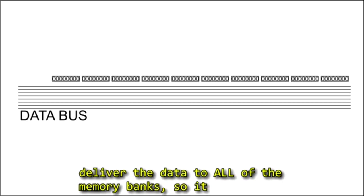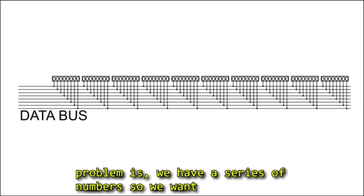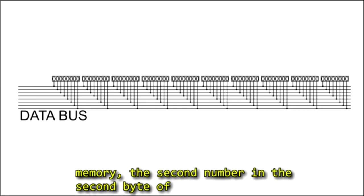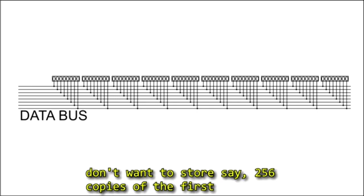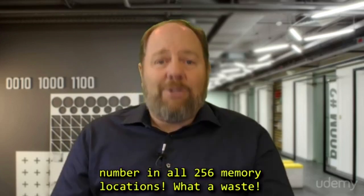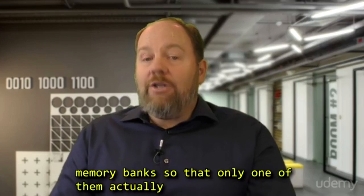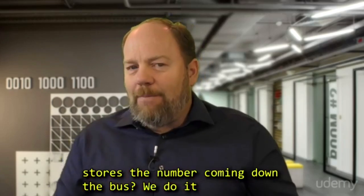Now it needs to be able to deliver the data to all of the memory banks, so it is connected to every single one of them. The problem is we have a series of numbers, so we want to store the first number in the first byte of memory, the second number in the second byte of memory, the third in the third byte, etc. We don't want to store, say, 256 copies of the first number in all 256 locations. What a waste. So the problem is, how do we turn on or off the memory banks so that only one of them actually stores the number coming down the bus?